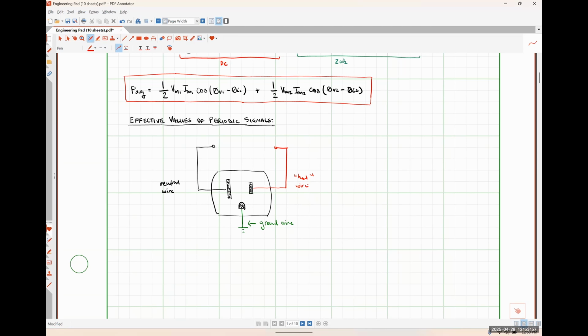Usually your ground wire and your neutral wire wind up tied together outside of your home in your literally like your lightning rod or ground spike. It's literally a piece of metal that's driven into the ground to give your home access to a true earth neutral or a true earth ground, and you tie your neutral to that in most forms of construction.